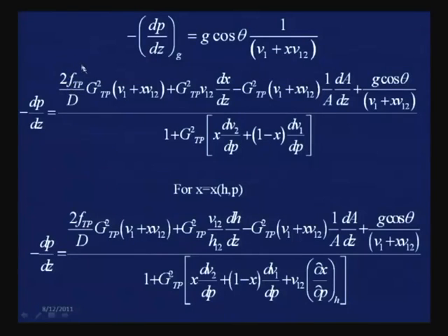So, therefore, the next thing which we would like to do is to discuss methods by which we can express the two phase frictional pressure gradient in terms of certain input parameters, or in terms of whatever we know for the case of single phase flow. We cannot idealize one particular definite unique method of defining FTP, we will be discussing the different methods.